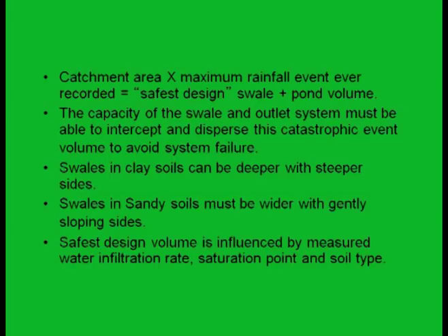We had 13 inches of rain in an hour once, and we swallowed it all up. It didn't leave. If you have a place with no swales, I don't care how on contour or keylined it is, when you get 13 inches of rain in an hour, it's going to go away. So we kept it on site. In clay soils, they can be deeper with steeper sides. Sandy soils, it's shallower. The safe design volume measured is influenced by infiltration rate, saturation point, and so on.